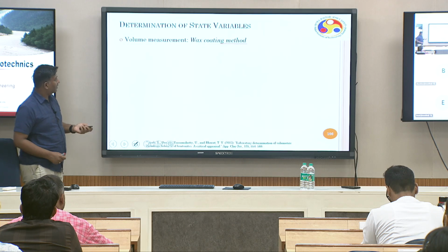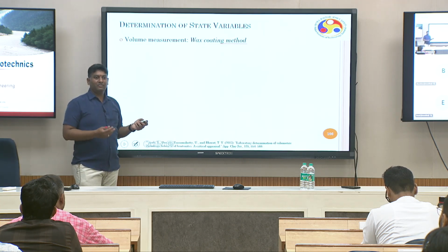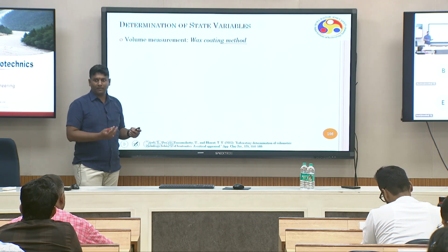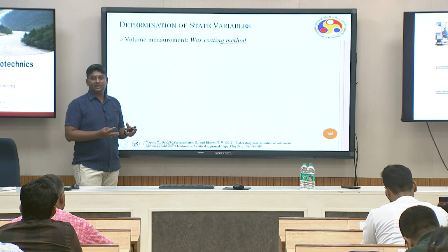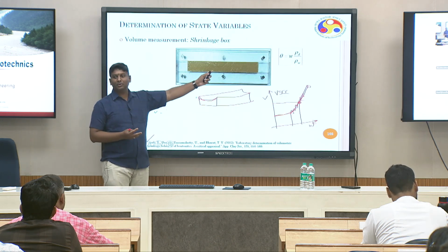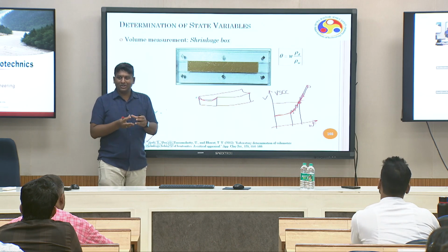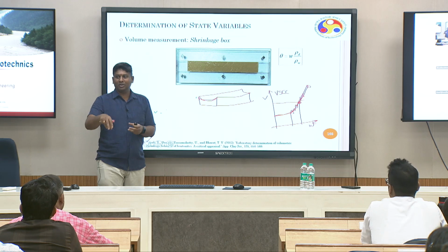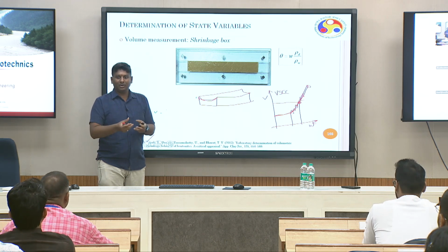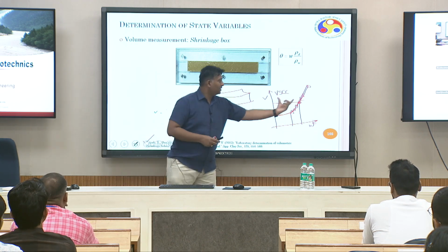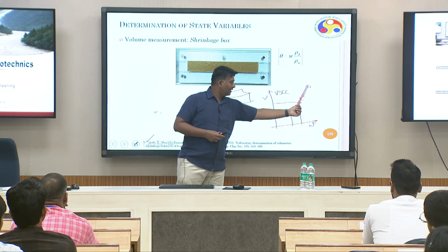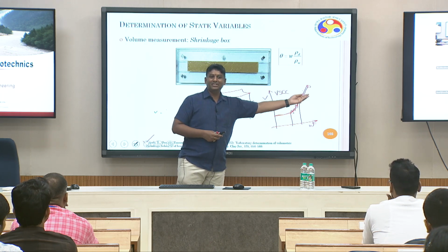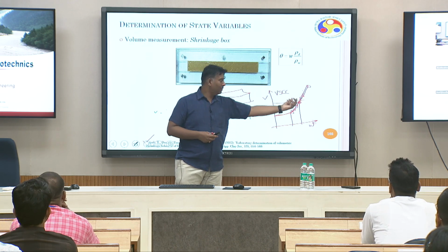Wax coating is one method we commonly use, because in the field also we use it, right? A field sample has to be brought to the laboratory. We use a wax coating. So look at the consistency. At this consistency, definitely you can't do the wax coating, because it should have good consistency where you can hold the sample and coat it. You put it in hot molten wax. For that, you require good consistency. So you will be missing some points here. Somewhere here you will start, right? Hopefully that is before the desaturation starts. Otherwise you will be missing a few points.